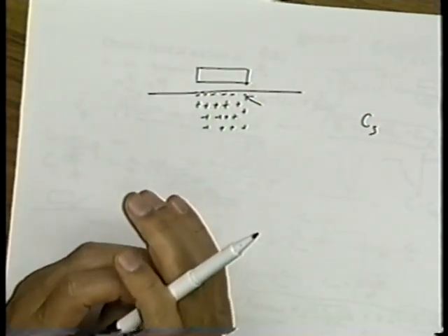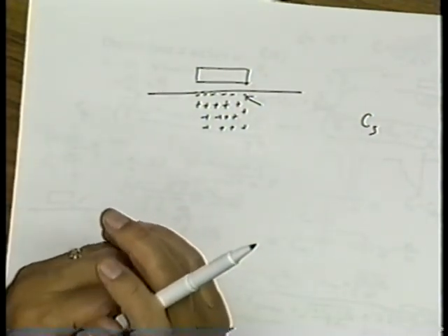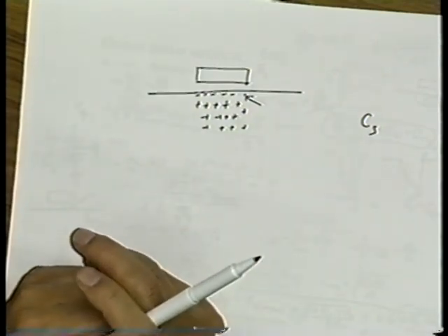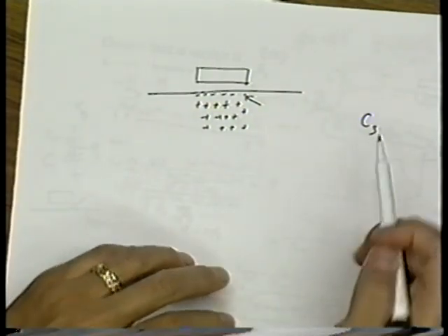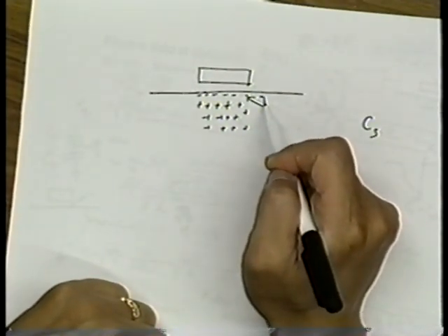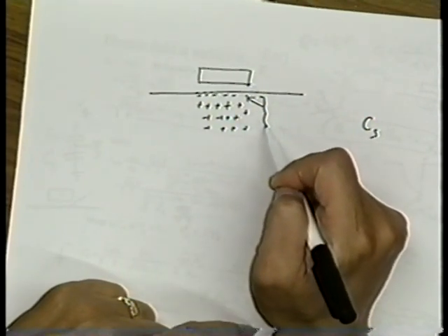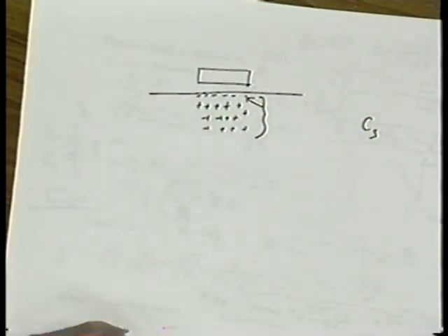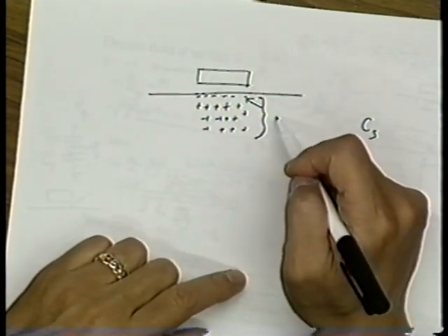Okay, all right. It's a mathematical boundary that we're using as the beginning point of our capacitor. And all of these, the inversion layer, accumulation layer, as well as the depletion layer, are part of our bottom electrode.